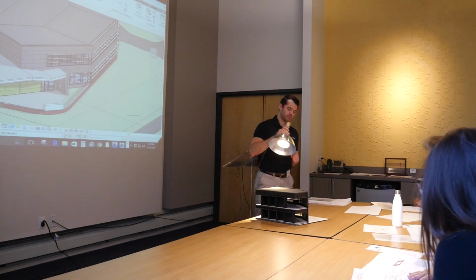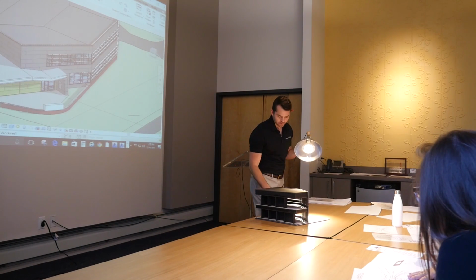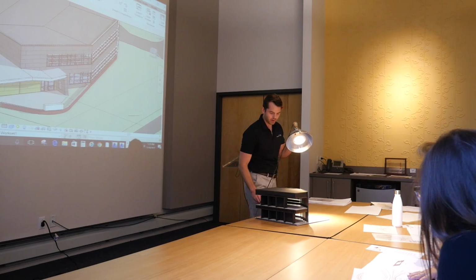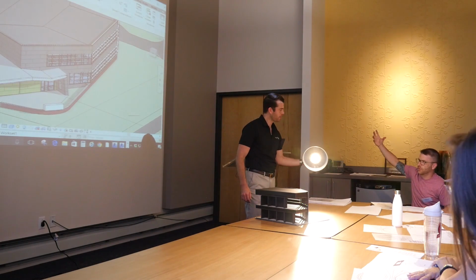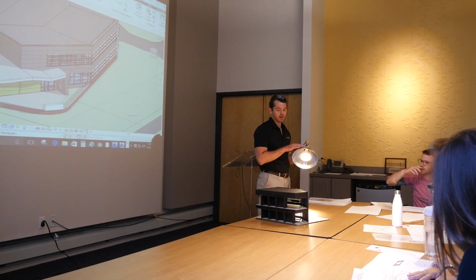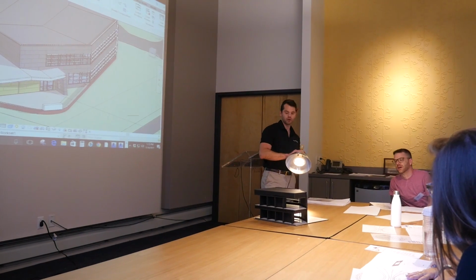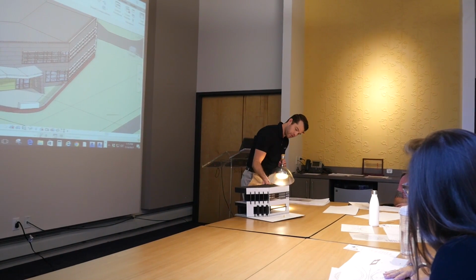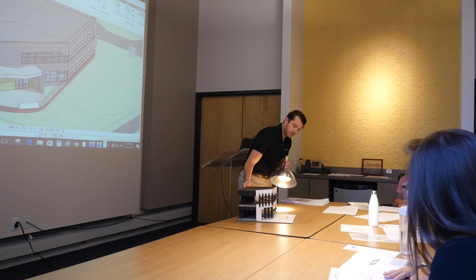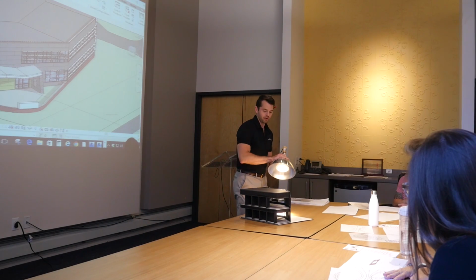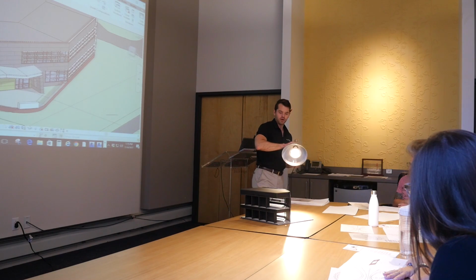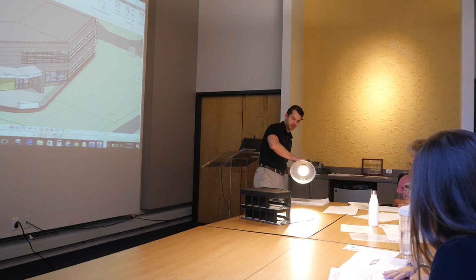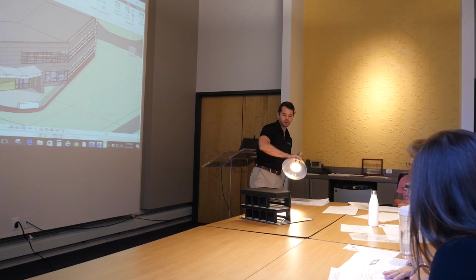These are great to use outside because obviously August at 10 a.m. is right there. You take that out. So using that chart, it tells you kind of where to hold your light source. So I'm actually moving the light source to tell me what time of year I want to see the shadows in the model. So this is an open office workspace in here. And if I want to see how bad those employees are going to get blasted, for example, in January in the morning, if I make the tip of that shadow of that peg hit that intersection of that time of day, it'll have the same effect of what the sun would do at that time of year.